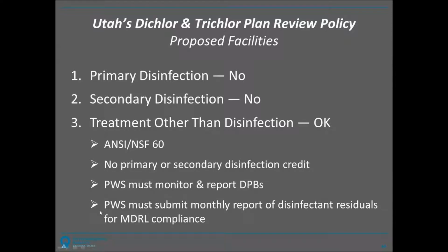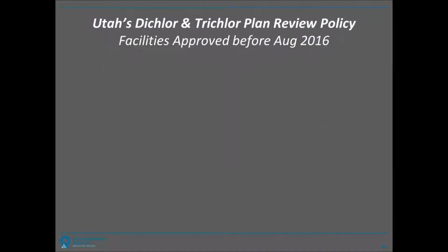First, we are saying there's no accurate analytical method to measure dichlor and trichlor concentration for disinfection requirement. However, we still need to check whether they maintain the minimum residual in the distribution system or whether they exceed the chlorine MCL requirements.